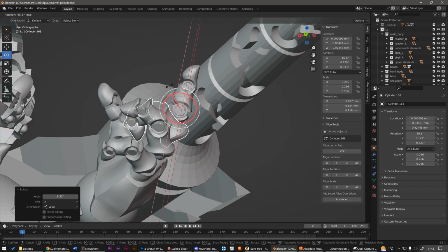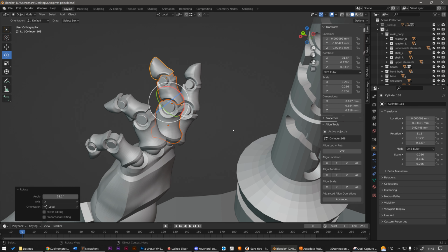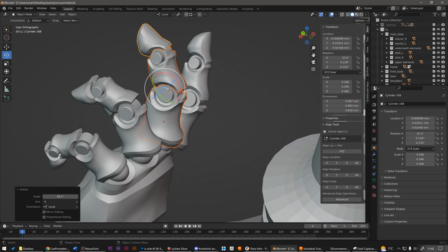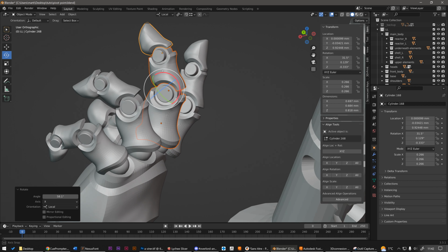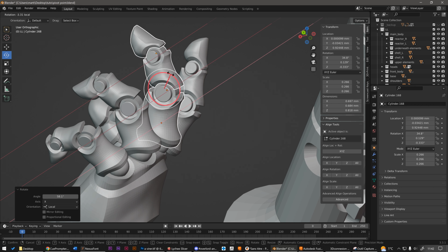In fact, what is happening here is, the joints are transformed with 2 cumulative rotations. A rotation inherited from the parent object, which uses the origin of the parent object. And this rotation is cumulated with another rotation around each joint's own origin. Very interesting for animating joints.